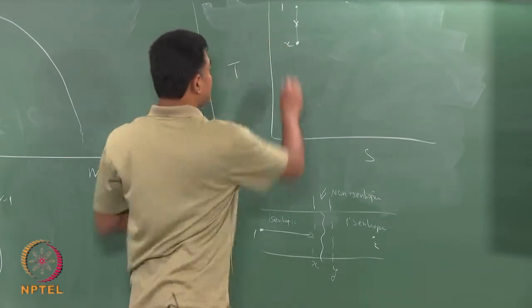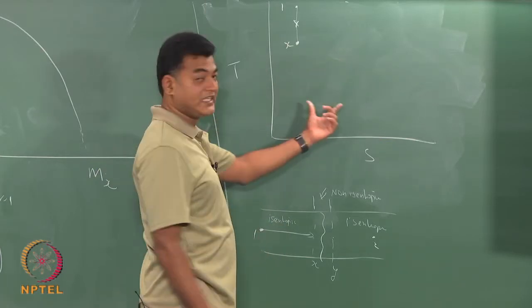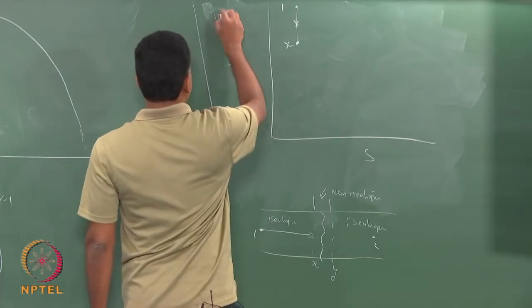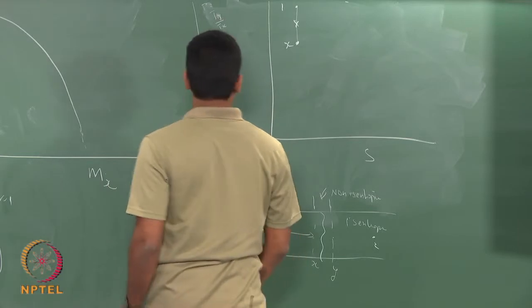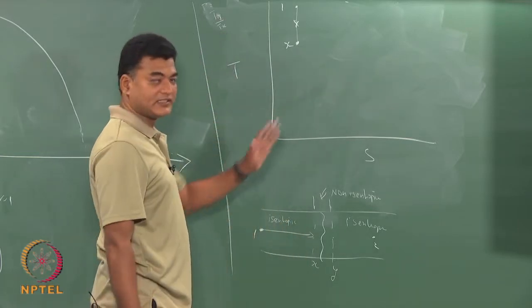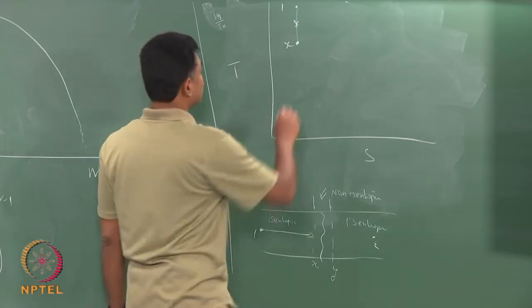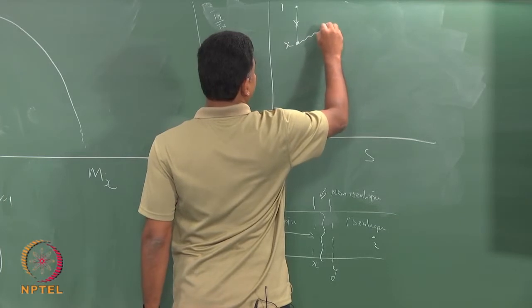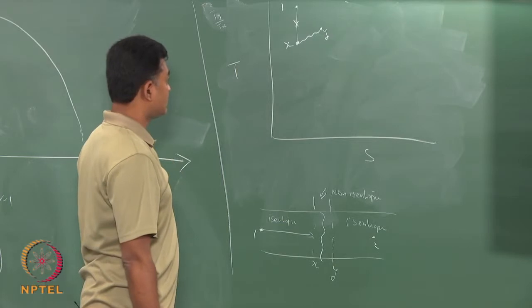Now, the moment it encounters a shock, there is an entropy change. So, there is a ds. So, if I take Ty by Tx, that is increasing. After the shock, it is increasing. So, my Ty is greater than Tx. So, I have a process that takes me to some location here which is my y. Okay.